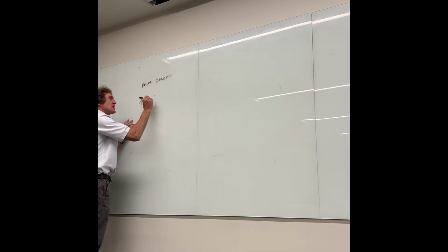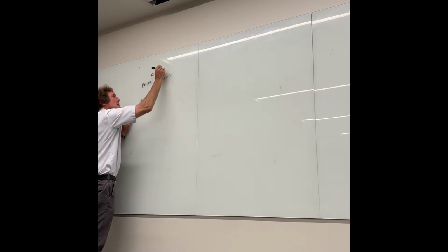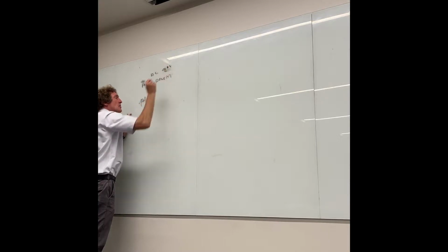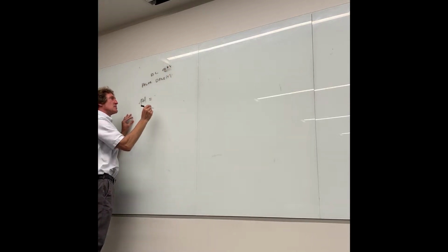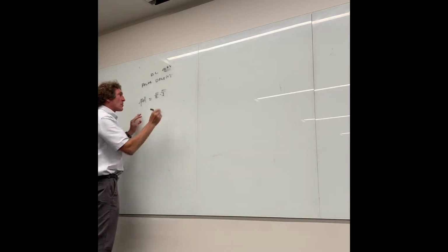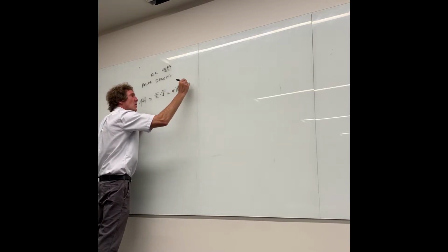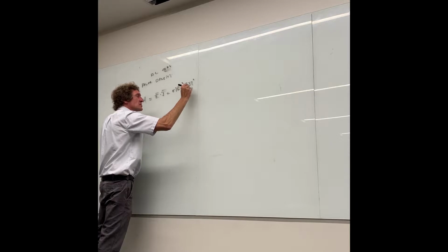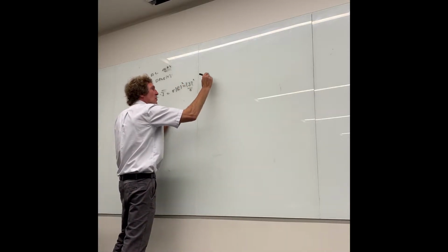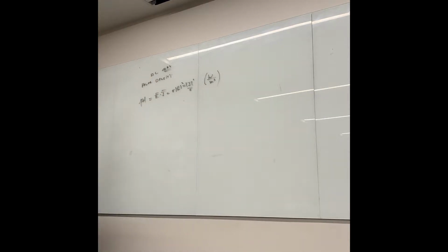Well, power density, this is for DC currents, by the way, DC only. This is not for AC. Power density is equal to either E dot J, or it's equal to sigma times magnitude of E squared, or magnitude of J squared over sigma, and the units are watts per meter cubed. Now, think about a power density. A power is in watts. A density is always going to be meter cubed volumetrically, correct, class?